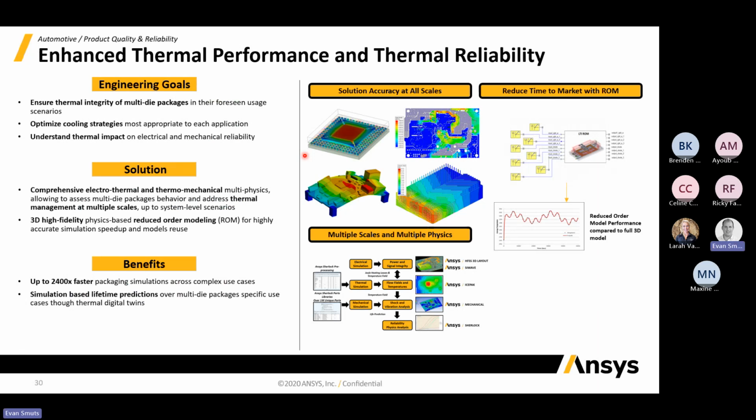Typically, your thermal loads are due to the operation of the components, like your power loss on the PCB, but they could also be a result of some sort of external condition, like hot air that's been blown over them from other equipment or just bad cooling design. And so we can bring in the thermal loads from both internal in the component as well as externally, and then try and understand where are we going to have any hotspots?